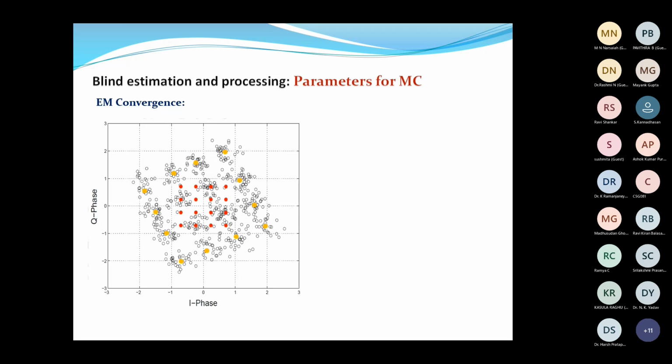Now we compare the amplitude of the outermost cluster center with the ideal constellation model. The ratio of these two gives us the signal amplitude. And next we can again have the phase difference between these two vectors, which directly gives us the estimate of the phase offset. This is a simple conversion, but it gives fairly simplistic estimates of these two parameters, which are required for our log likelihood function determination.